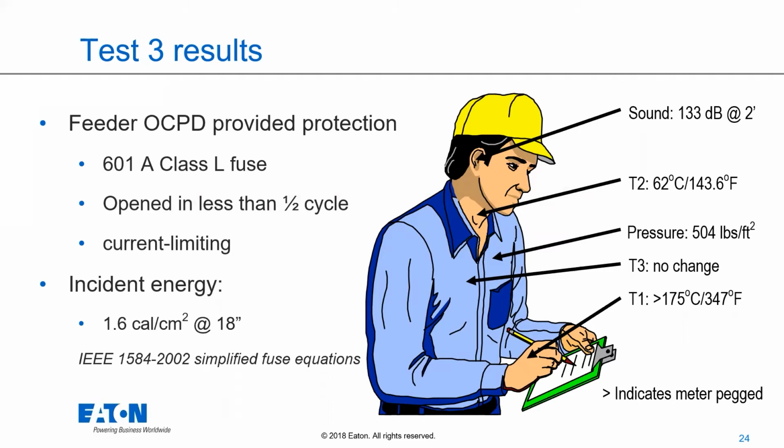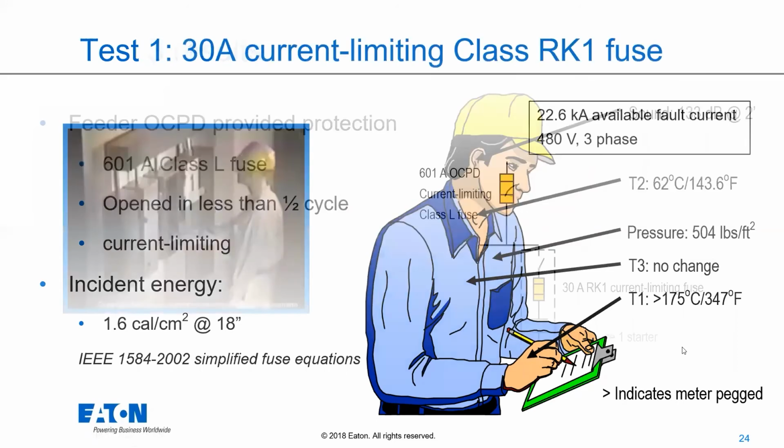The pressure is a lot smaller. No change in temperature underneath the t-shirt. Now the hand was reaching into that cabinet as close as it could be. It still saw high temperatures, right? That could still be a 3rd degree burn on the hands if there's no additional PPE. But there's a reduction in everything you can see here on the right, except for that hand, as far as the amount of health damage it could do to a person standing in front of it.